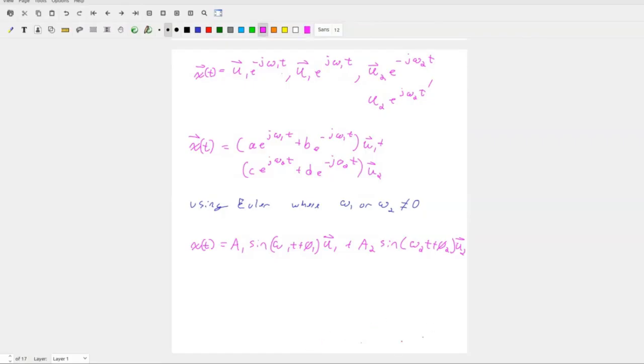And that is an expression as long as omega 1 or omega 2 is not equal to 0. We can write that in matrix form, but I'll let you do that or take a look. This is 5.36 in the text. I'm going to draw a red box around that one. It's pretty important. Again, A1 and A2 can be obtained by applying the boundary conditions and taking the derivatives of the equations, as we did in a 1 degree of freedom problem.